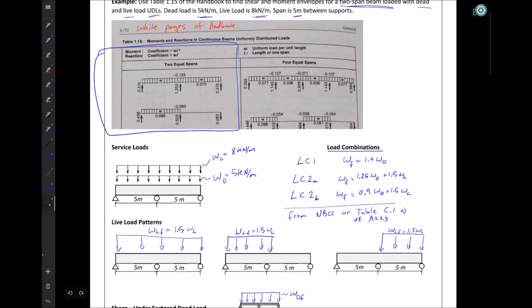So now if I take those individual scenarios and add them to here, I would have 3 different shear diagrams. But I'm not going to do that. Instead, I'm going to look for worst case scenarios that come out of here and add them to worst case scenarios that come out of these ones here.